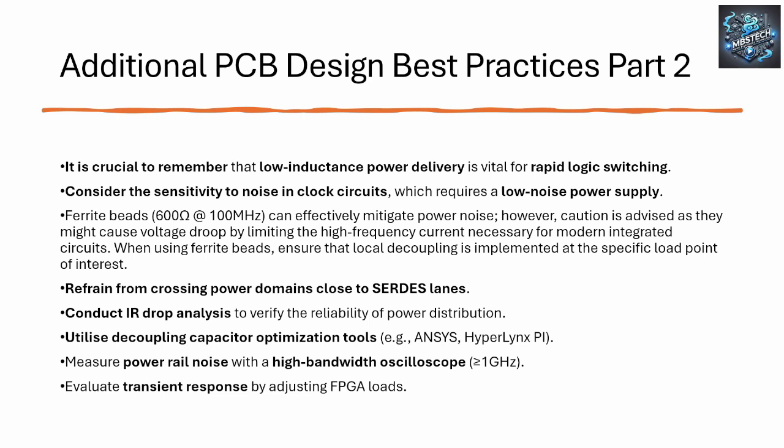Conduct an IR drop analysis to verify reliable power distribution, and use decoupling capacitor optimization tools. For instance, ANSYS, HyperLynx, CST. Those are all power integrity and SI, signal integrity, tools. If you've got the availability to use them, I suggest you use them. It is also a good way of closing the loop from the hardware to the simulation point, so you can actually start to trust the tools.